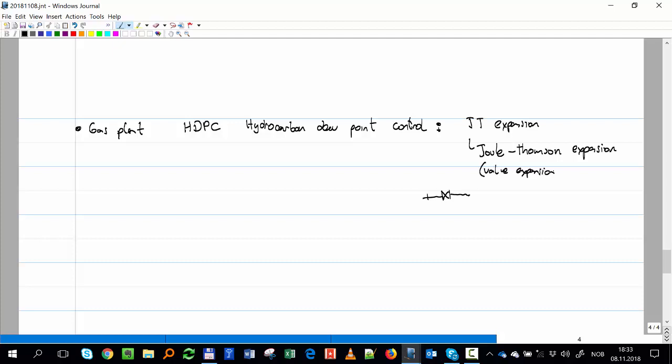And Joule-Thomson is the name of this phenomenon that in a gas, when you reduce pressure, the temperature also drops. You have it also in a pipeline. In a pipeline, it might be that at the inlet the gas is 70 Celsius, and after a long time it might come even lower, to the ambient temperature, just because of this Joule-Thomson effect.